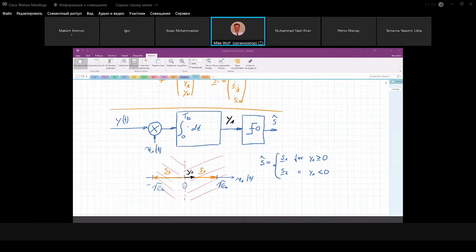And then we said for this antipodal transmission, where this is our signal space, if we then use this minimum distance criterion, we can say any vector which points in the positive direction, as can be seen here in this example, is closer to S1 of t, let's say, compared to S2.